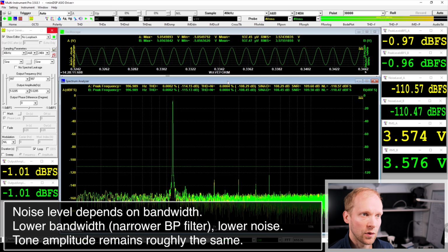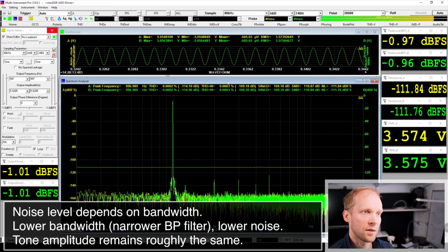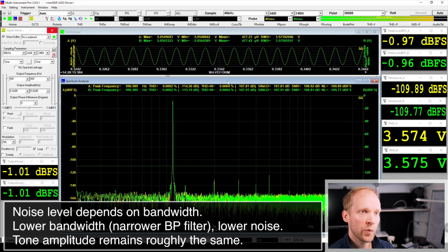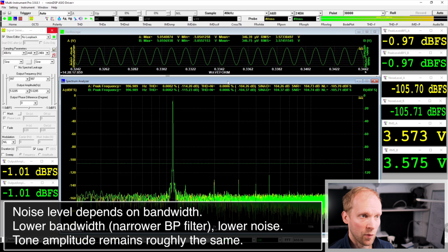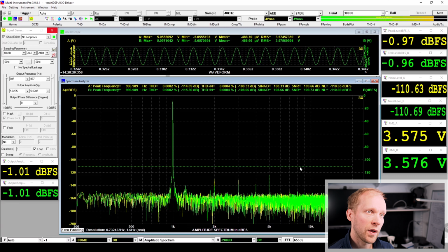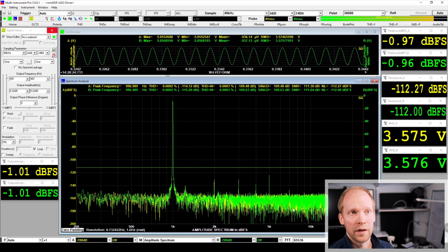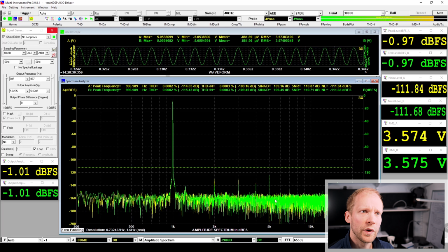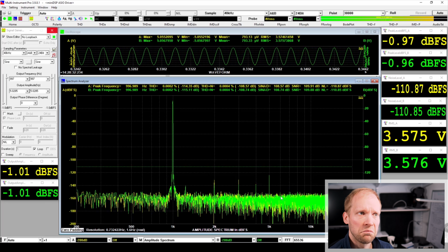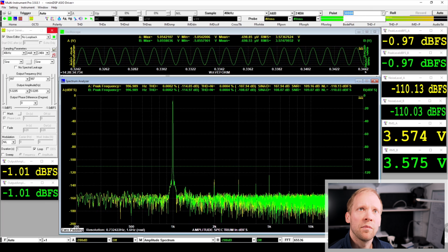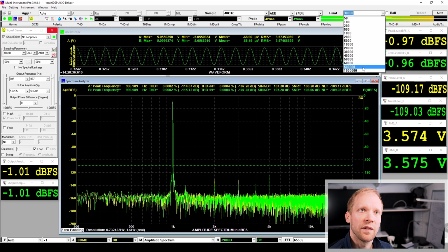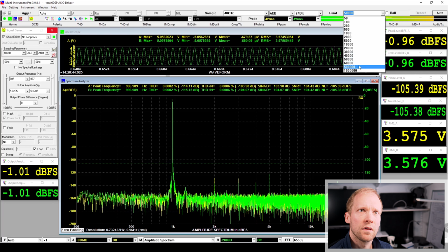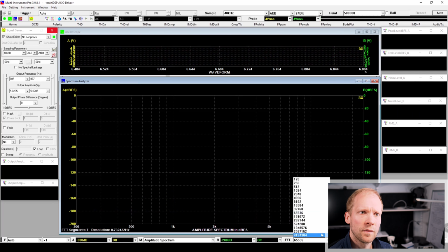You always need to look at noise within a limited bandwidth. When your bandwidth goes smaller, your noise gets smaller as well. And that's one way to dig out these distortion components in the signal. That, okay, let's see, we don't see the sixth harmonic now. It's under the noise. Okay, what happens if we take a very long signal, a lot longer than that.